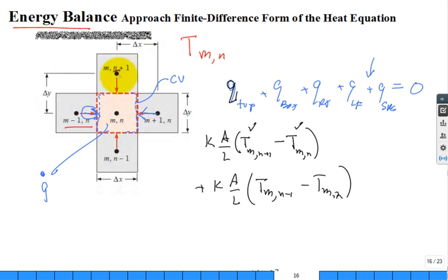If I'm looking at going from top to the center, inside, what is the area for the heat flow? It's my perpendicular area, isn't it? Would it be the product of this distance right here times the depth in the third dimension? So the area would be the distance delta x times a depth in the third dimension. I'm going to call delta z. But you know what, delta z, you can pick it to be 1, or in the equations, all the delta z's will cancel.